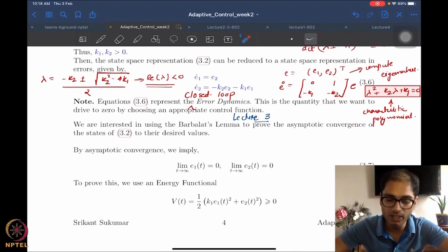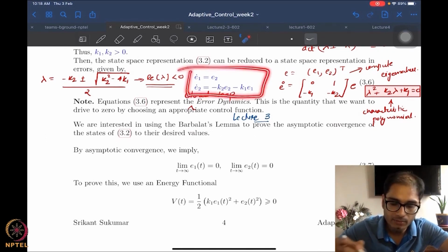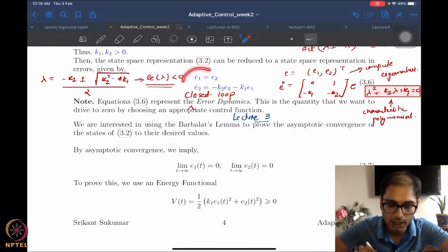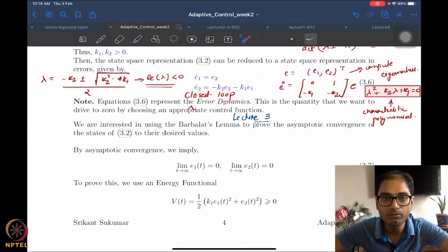Because it's obvious that in this case we have other tools like your eigenvalue analysis, your Routh-Hurwitz criteria. You have so many methods to in fact conclude exponential convergence. Why do we need potential functions? The point is, in a lot of cases, our target system turns out to be nonlinear. You may have to make your target system nonlinear. You have no choice.